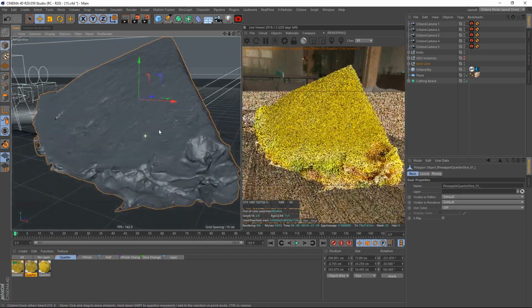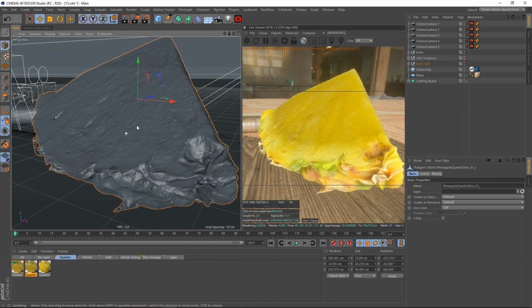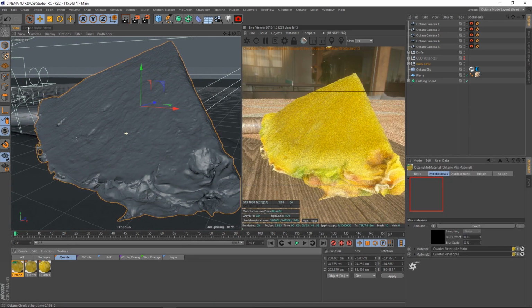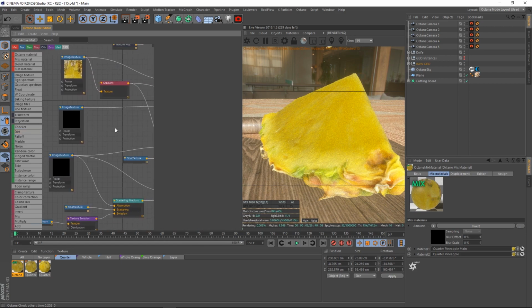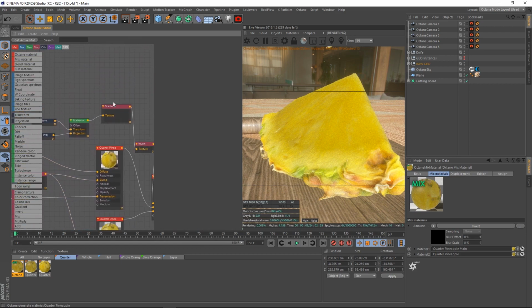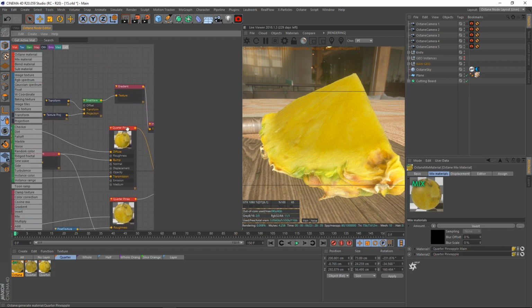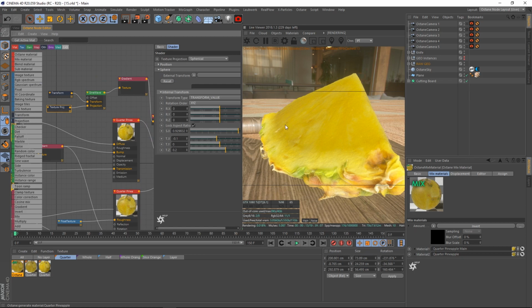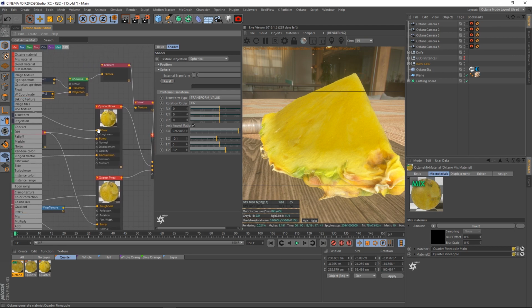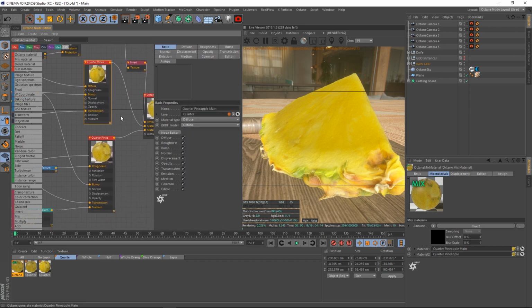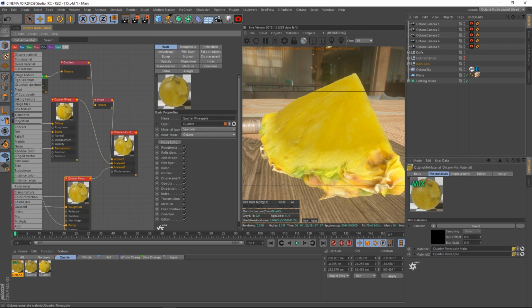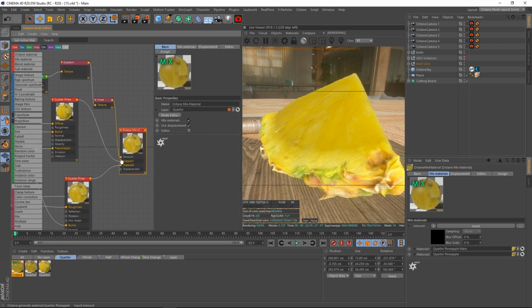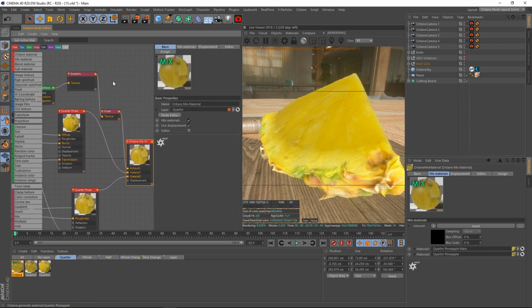So what I did, essentially, is I took an Octane mix material. We'll go ahead and select that now. Up here, I actually used a gradient and did a circular projection. I did a radial projection with a sine wave, and with my texture projection, I did a circular gradient on this. Now, to help make this apparent, I'm going to take our diffuse, because here's our diffuse. Here is our specular, and they're both plugged into this mixed material, and the amount of each that shows up is controlled based off this gradient.